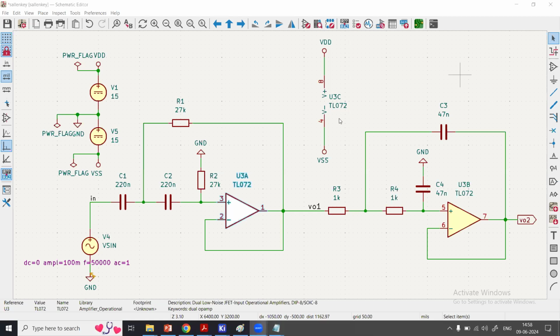So everything is set now. We have very well covered the SPICE modeling part, calling it into sub-circuits, and calling the sub-circuit twice. And once that is done, the circuit is ready. As I said, this is a high pass filter and this is a low pass filter, and cascading the two will form the response of a band pass filter.